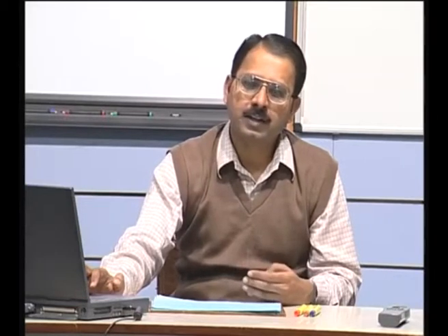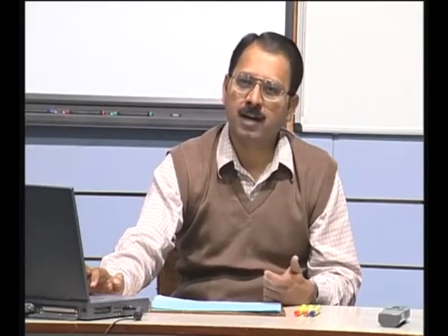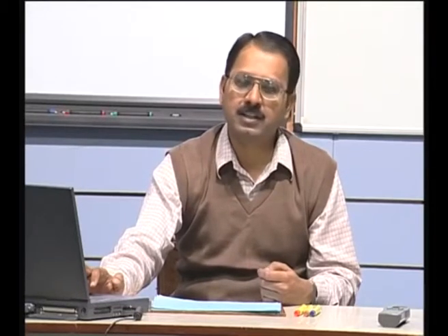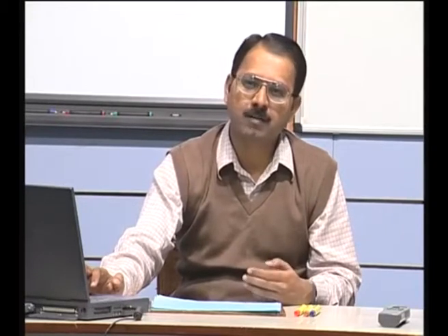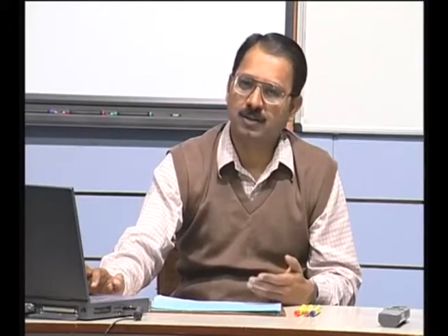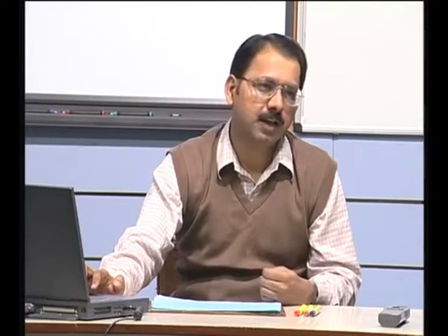Now, this is important. If I do not have a good estimate, then I have to purely do it based on one's own past experience, which may be very, very conservative in some cases. So, the actual solidification time may be x, but you may be removing the part after time like 2x. So, it is not a very productive kind of situation. If I have a predictive model which can tell, if this is the material, this is the volume of the material, this is the geometry which is being cast, what would be the solidification time, that helps me in terms of efficient process planning or arriving at optimum process plans.